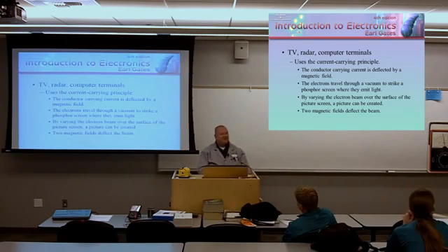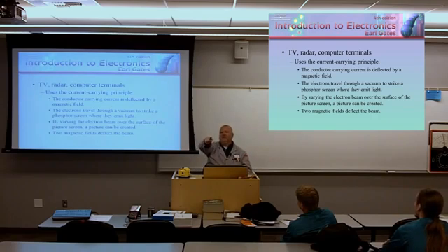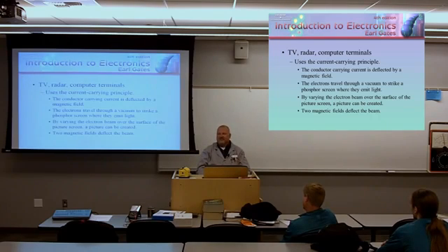Now, an electron gun basically sits in the back of a cathode ray tube and shoots an electron beam out towards the screen. That electron beam is going to be controlled through deflection windings. The deflection windings are horizontal and vertical. And that's what's going to be used to basically paint the image on the screen. It's your x-axis and your y-axis. So that's how we'd use that to paint an image. Now with flat screen monitors, we're doing things a little bit different, but it's kind of an evolutionary process based on what we were doing with that magnetic field.